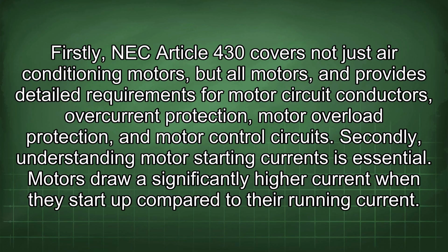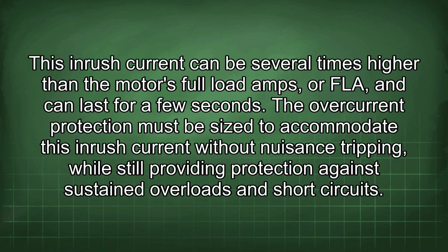Secondly, understanding motor starting currents is essential. Motors draw a significantly higher current when they start up compared to their running current. This inrush current can be several times higher than the motor's full load amps, or FLA, and can last for a few seconds. The overcurrent protection must be sized to accommodate this inrush current without nuisance tripping, while still providing protection against sustained overloads and short circuits.